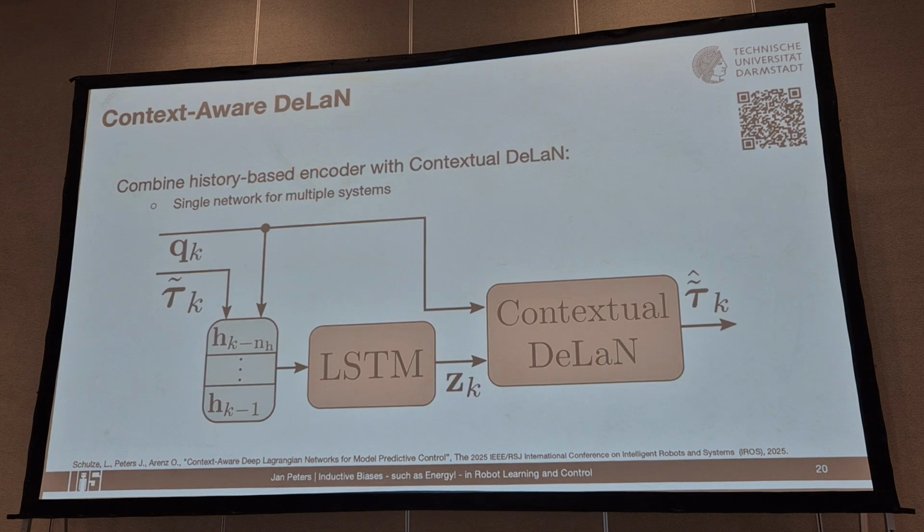Context is for us really powerful, because with the context we can now create trajectory statistics, for example, using a long short-term memory neural network. And these trajectory histories enable us to cope with things which are flexible, like something which isn't perfectly attached, or even a flexible link between 2 joints, and deal with the trajectory statistics as if they were another variable in our dynamics model.